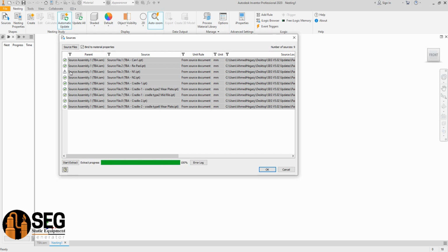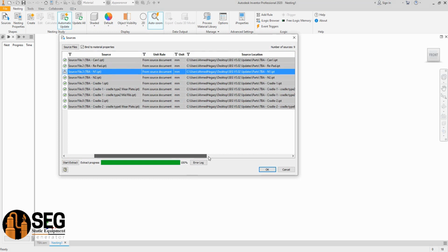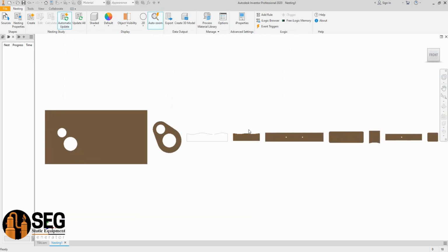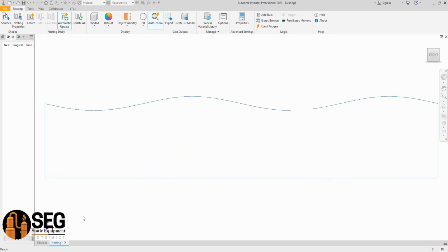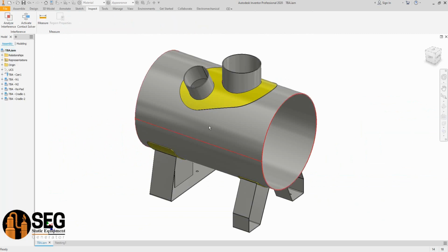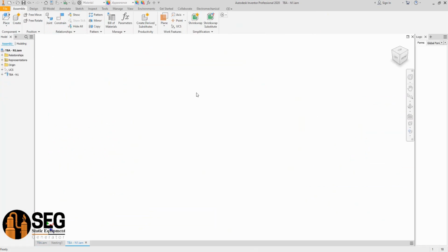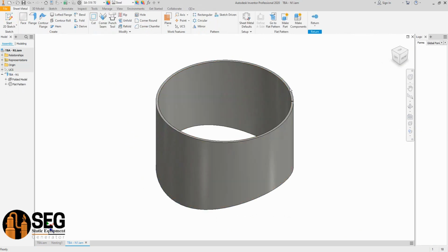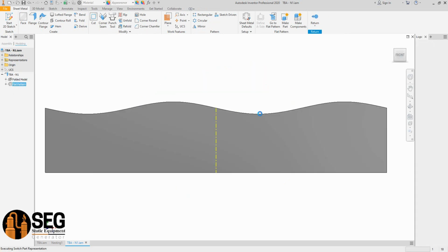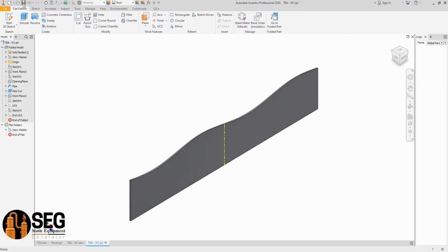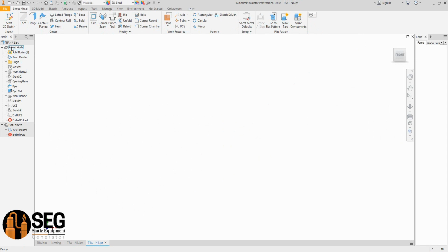development for the parts. Now, as you can see here, we have an issue with that part, which is nozzle N1. And now let's accept this. We need to check the issue with that one. So let's open part number 1. And from here, let's go inside that part and create the sheet metal development for this one. I think it's okay, no issues with it.